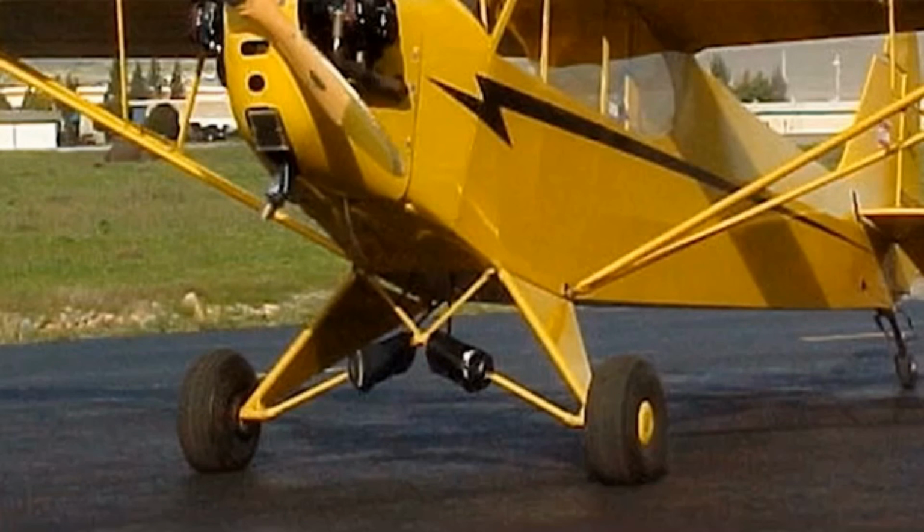Tyres must be protected from excessive heat, dampness, bright sunlight, contact with oil, fuel, and hydraulic fluid. All of these have a harmful effect on rubber. Covers should be placed over the tyres when the aircraft is to be parked for any length of time, or during the periods when oil, fuel, cooling or hydraulic systems are being drained or replenished. Any fluid inadvertently spilt or allowed to drip onto a tyre must be wiped off immediately.